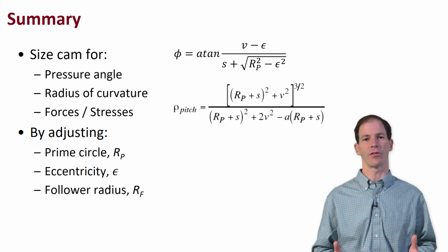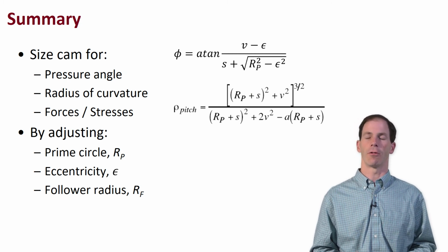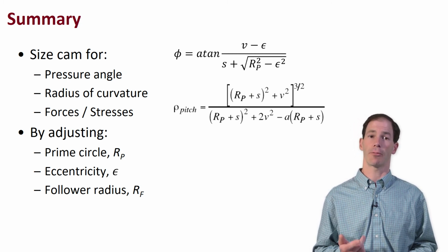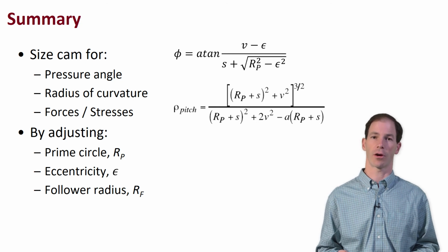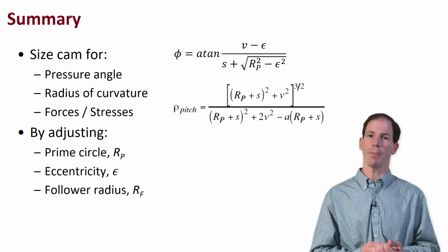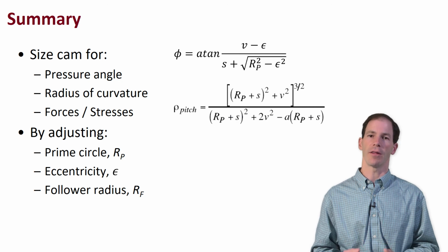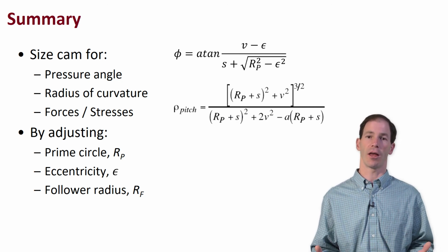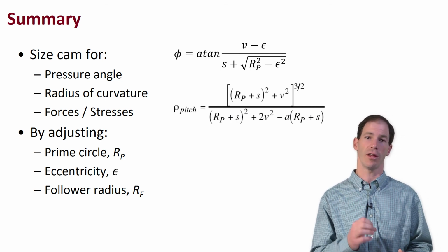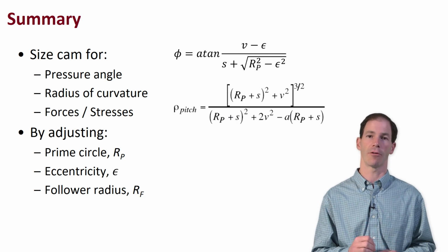So let me just summarize now. What do we size the cam for? Well, first of all, we focus on the pressure angle and then move on to radius of curvature. Those are really the only two that we paid much attention to today, but the next major step is to then do a force analysis and specifically look at the stress in the roller to cam interface.